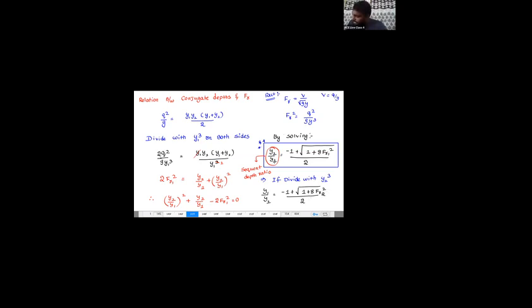You see, whatever the denominator is there, right? If it is y1, Froude number is going to be Fr1. And if it is y2 in the denominator, Froude number is going to be Fr2. But I use this sequent depth ratio only because we know the incoming flow, that means pre-jump. The pre-jump depth is going to be y1. And we know the incoming flow Froude number Fr1, which is going to be supercritical flow, Fr1 greater than 1. And based upon this, we are going to say the type of the jump also. Keep that in your mind.